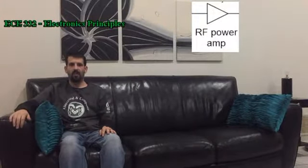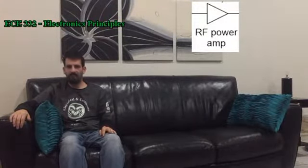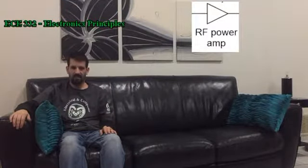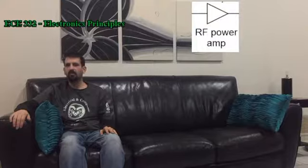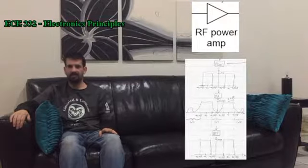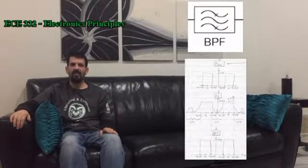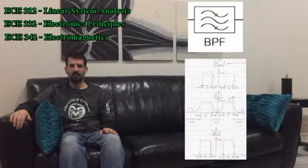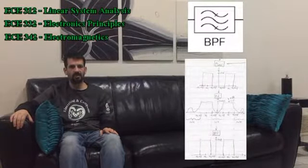Due to the second order effects of the power amplifier, the output signal contains the modulated signal as well as multiple harmonics of it at other frequencies. These all need to be removed. The bandpass filter is in the next stage before the antenna, which removes all of these unwanted harmonics. The bandpass filter incorporates knowledge from all 3 ECE courses.